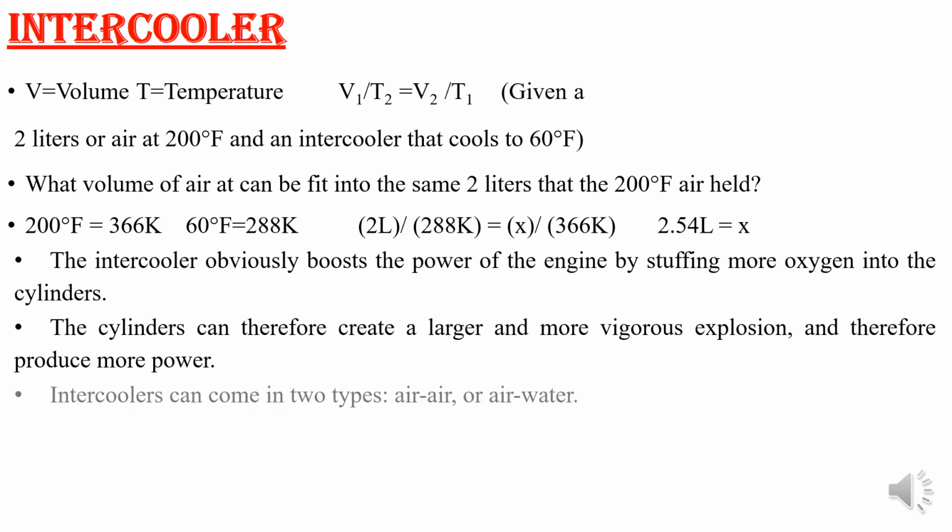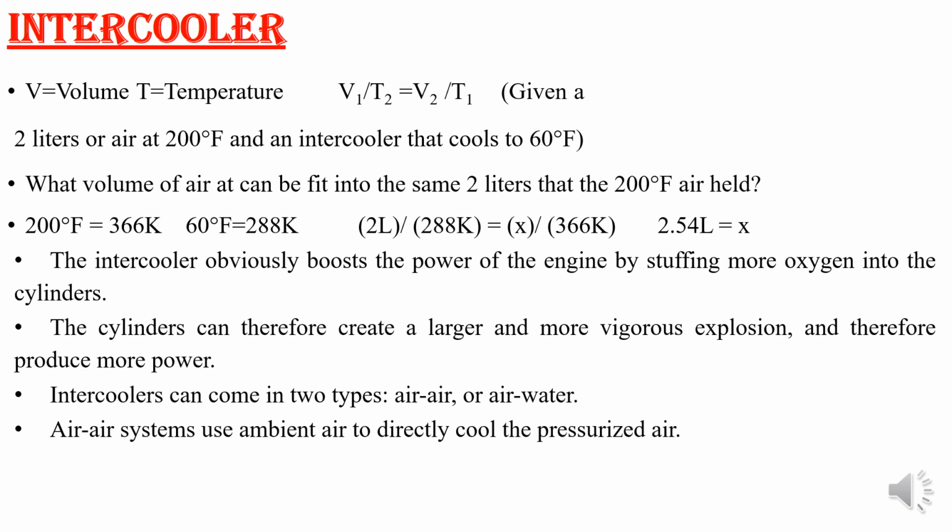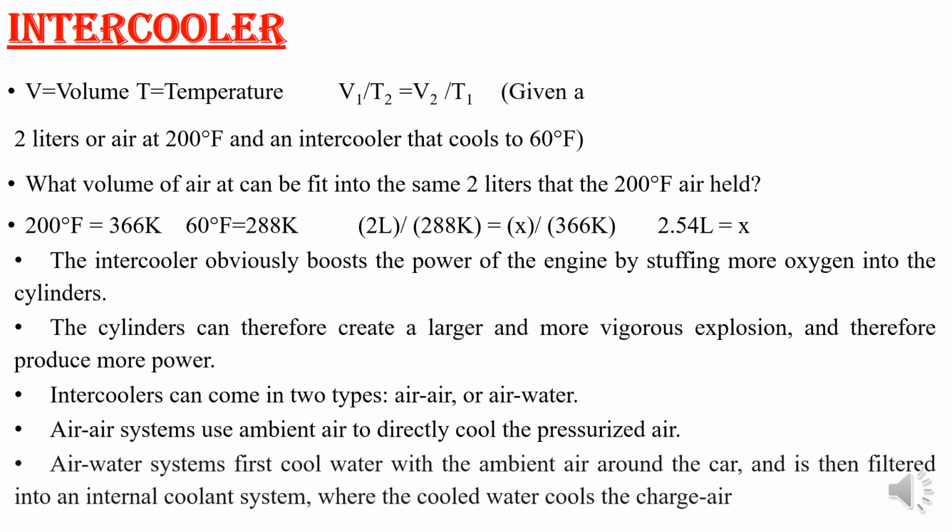So intercoolers come in two types: one is air to air and the other is air to water. In the air to air system, ambient air directly cools the pressurized air. In the air to water system, first the water is cooled with the ambient air around the car, and then it is fed into the internal coolant system, where the cooled water cools the charged air.